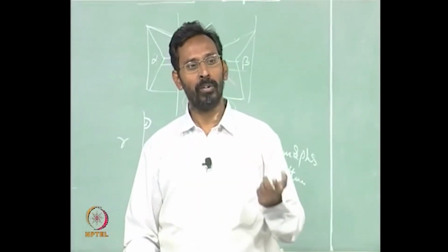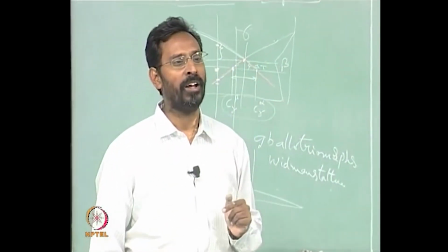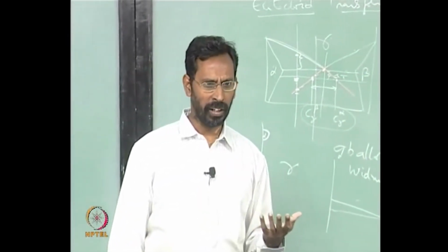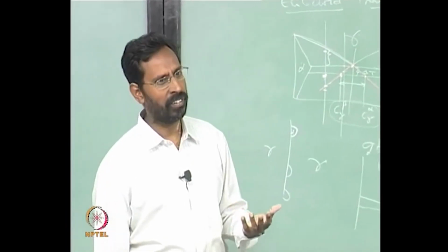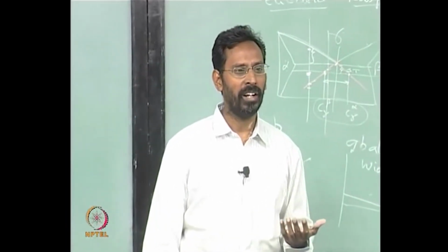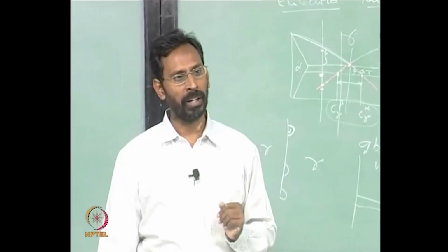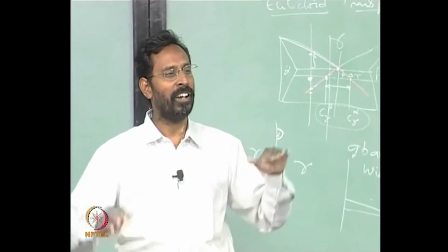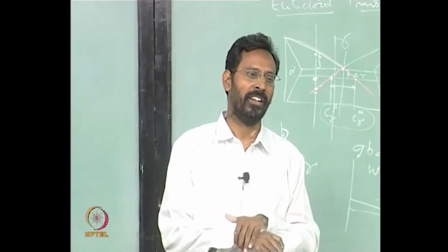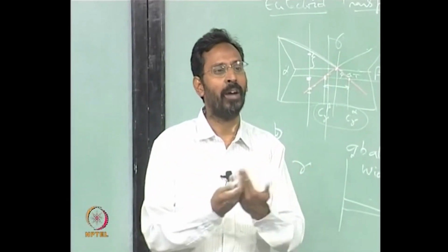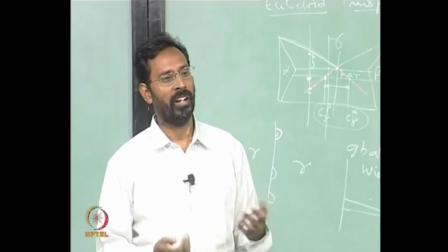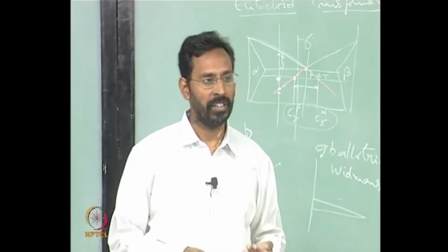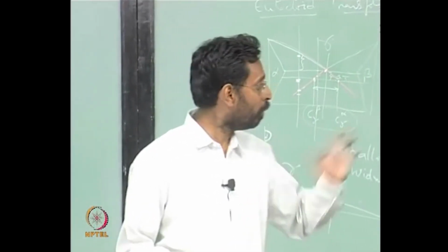In aluminum copper, 2 solid interfacial energies are lower, basically because one is the theta phase and alpha is the cubic, but if you look at high temperatures, the interfacial energies of both of them are close to each other. In fact theta is not even orthorhombic, it is BCT, it is tetragonal, sorry, orthorhombic is Fe3C.